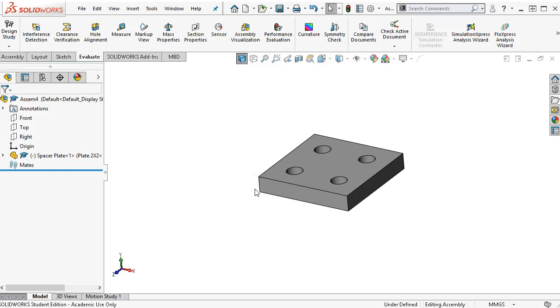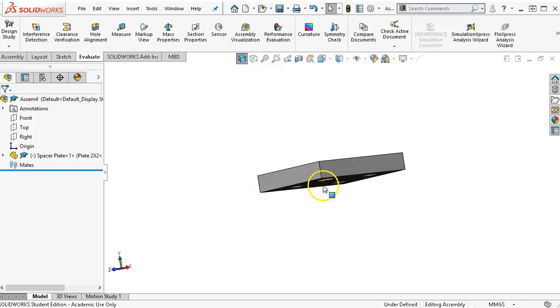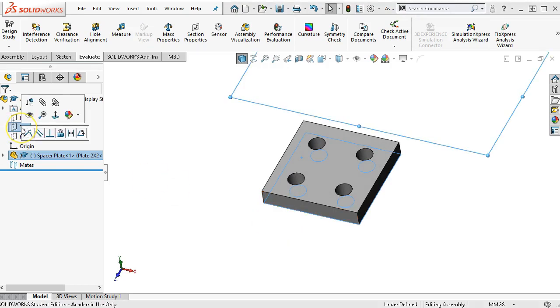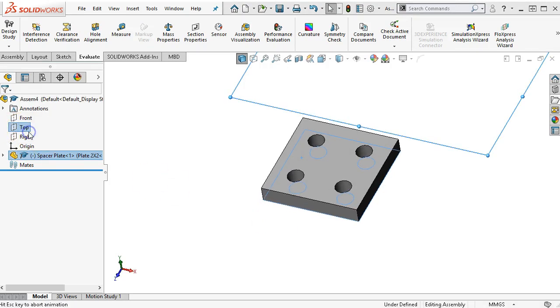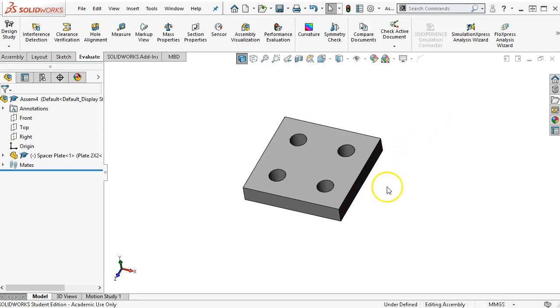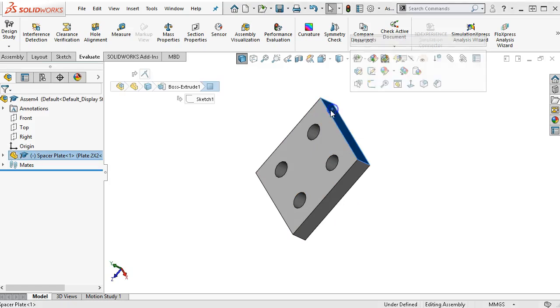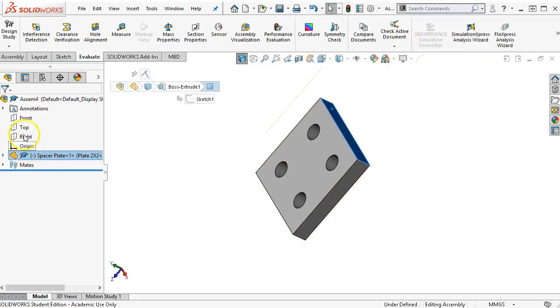So when I was creating the plate, I mentioned that we were drawing in the front. This is the result now of, I'm going to have to float these, put them into position. If we had drawn it in the top plane and gone through the process that way, then very likely these would come in oriented. I would hit the checkbox and it would go right to origin.